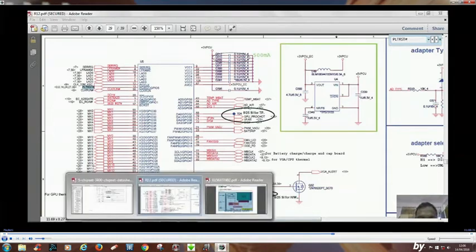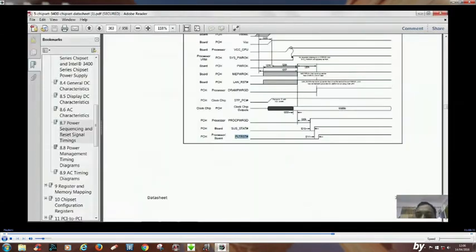After this, the CPU will read the first address at the BIOS chip, and this is how we trace a motherboard. So the first step is to identify which kind of Intel chipset is present. If it is a north bridge south bridge type board, identify which south bridge is present.